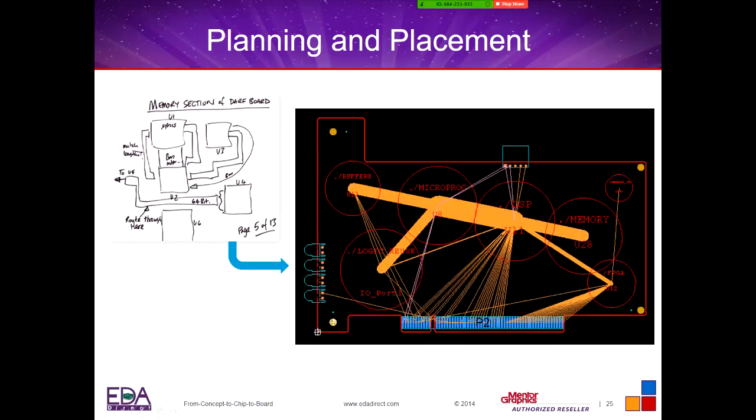We can actually set things up in our schematic, set up clusters per page, and then when we bring those sections in, maybe like a buffer section or a memory section, we can do some planning on here. And then all the parts will be inside of that circle, so it's easy to pull those right out. This is really nice in helping you plan your placement on your board. You're going to see a bigger difference than what you see in the PADS tools.